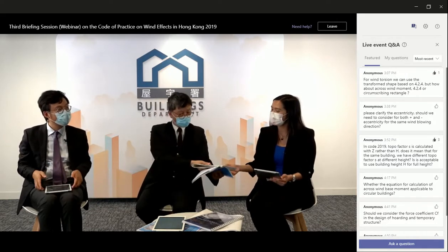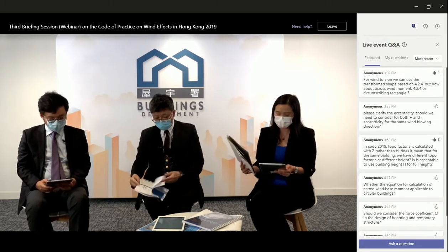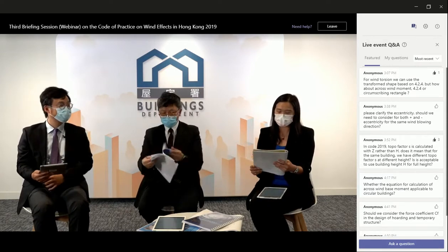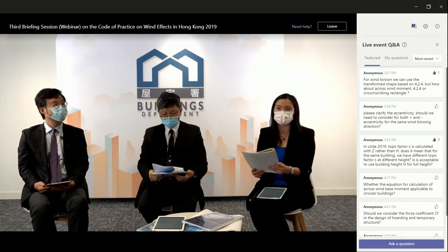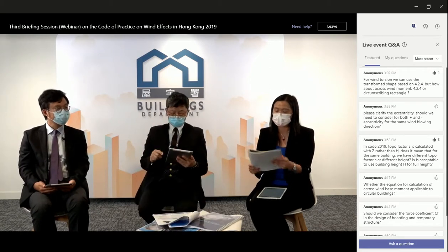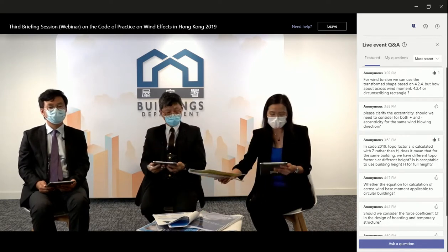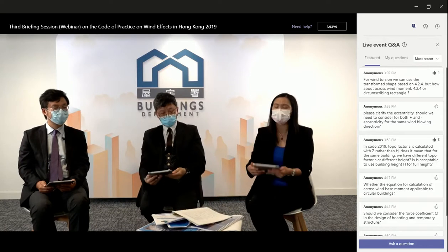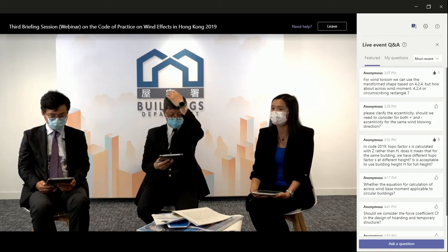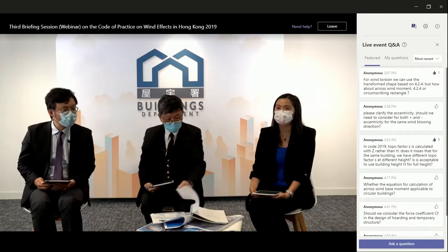4.2.4 is talking about how to calculate the pressure force coefficient of a building, and for this case, we show a lot of examples of how to calculate the B and D. You may need to note that this B and D is also applicable for calculating the torsional load. But this is not the B and D for calculating the across wind. It's not the enclosing rectangle. Maybe Natuni can supplement a bit on this.